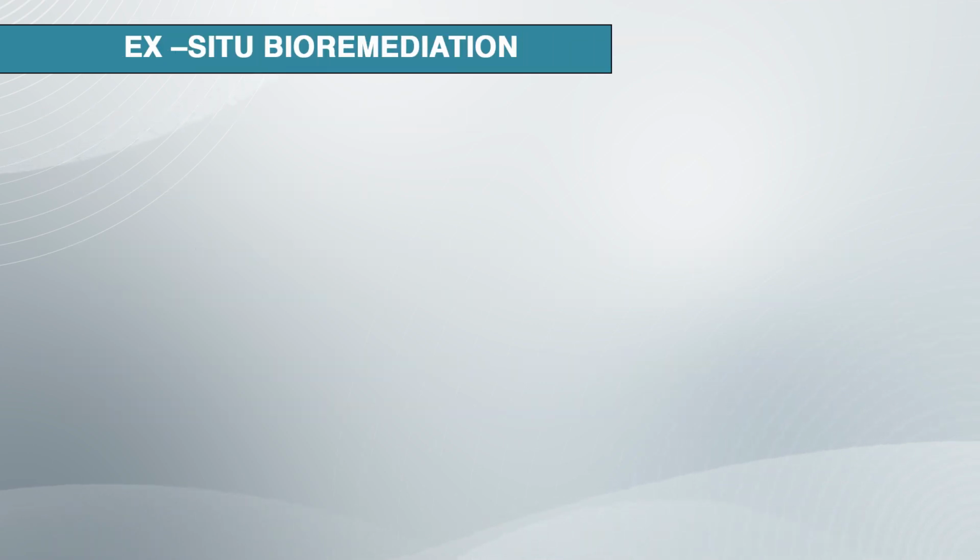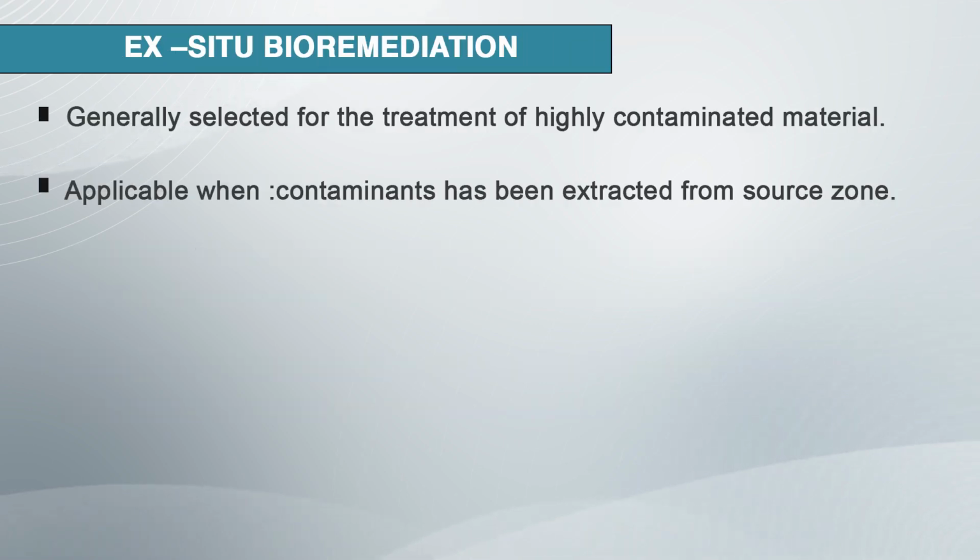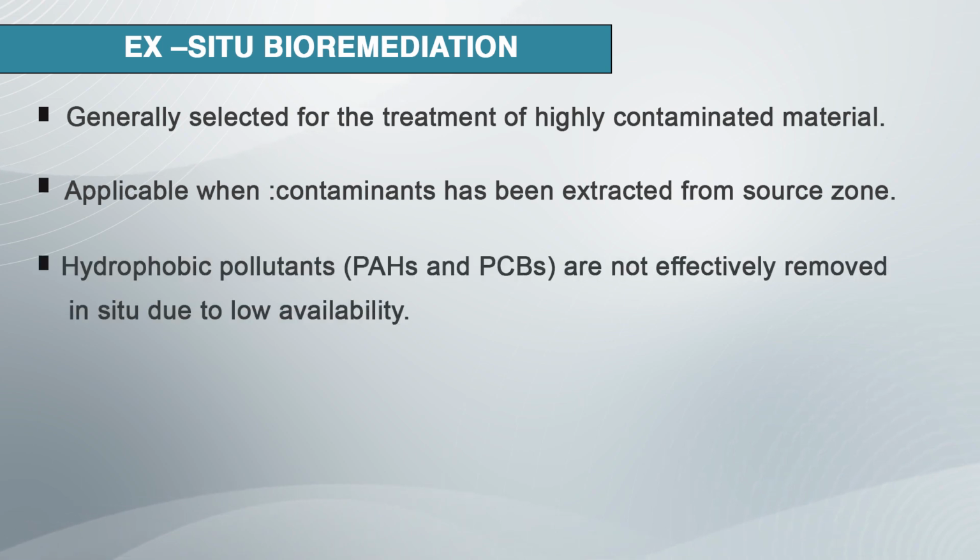Ex situ bioremediation: generally it is selected for the treatment of highly contaminated material, and is applicable when contaminants have been extracted from the source zone. Hydrophobic pollutants such as PAHs and PCBs are not effectively removed in situ due to their low availability.